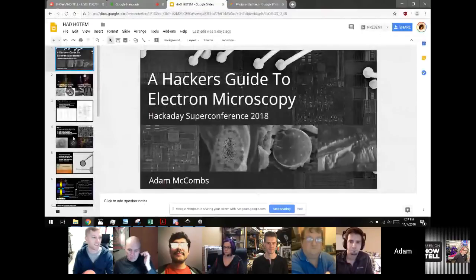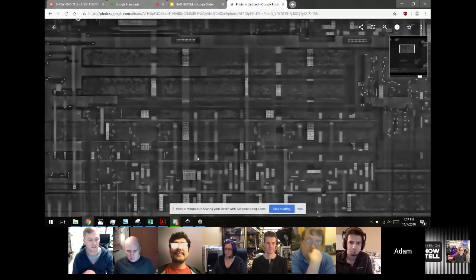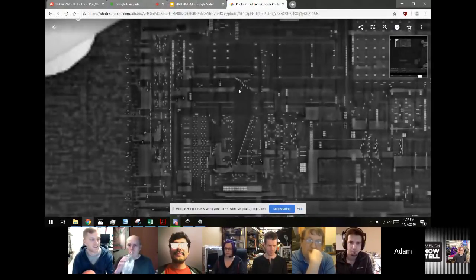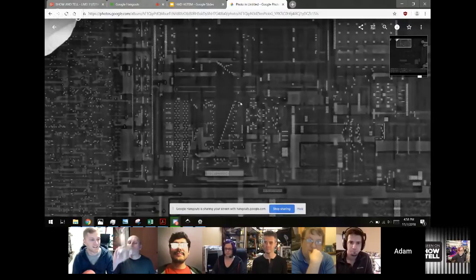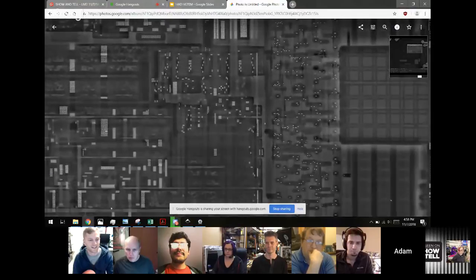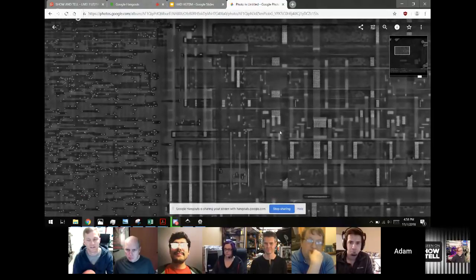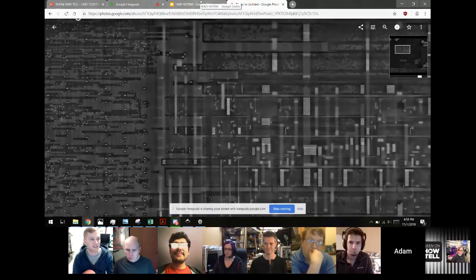The surface of the chip looks like, as I'm going to shamelessly pull a slide from my talk I gave at SuperCon, it has all these pitted surfaces and details that are a result of the acid etching. But by using this higher kV beam and a special detector, we're able to punch through that and gather a lot more information about the chip without having to continuously delayer it. And when you have something this high resolution, you can do some really interesting mapping efforts. You've got all these shift register type things here. You've actually got some areas where all these little bright white spots represent tungsten vias, and you can be fairly certain they're actually storing data in the chip. Which is always a lot of fun, to see those flags physically set in the silicon.